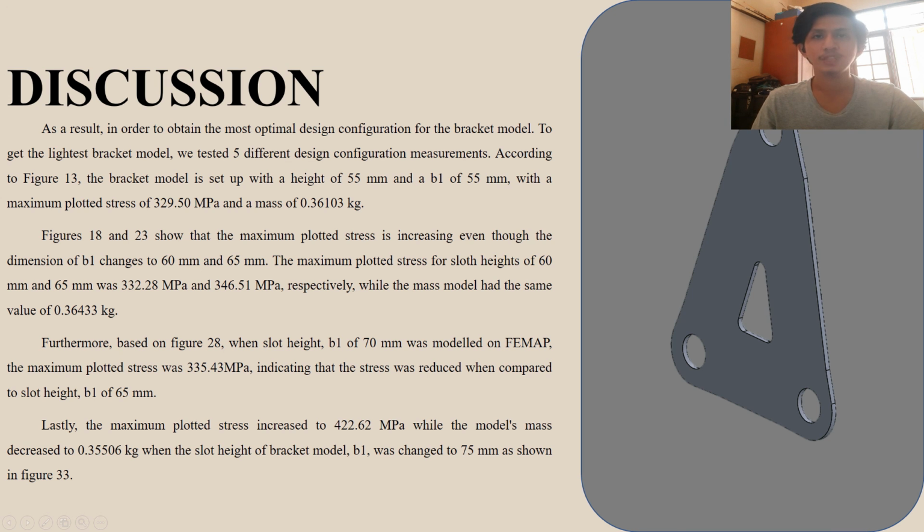The maximum plotted stress for the height of 60 mm and 65 mm was 332.28 megapascal and 346.51 megapascal respectively, while the mass model had the same value of 0.36433 kilogram.